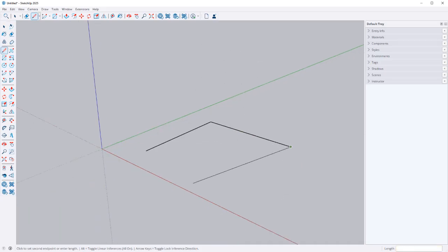Now, one other thing: a lot of you picked up the reference tools in AutoCAD pretty quickly. We've got a lot of the ones in here too, and pretty much all of them are on by default. So right now, if I start a line right here, I have this green dot. This is going to be an endpoint. Midpoint is that teal dot. Anywhere that I have a line going off in a similar direction, it gives me that fuchsia line right there.